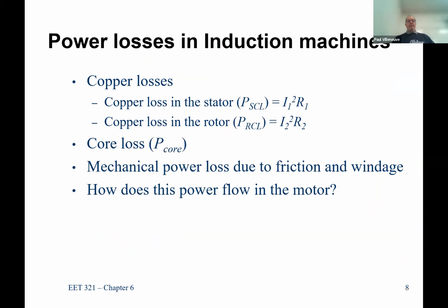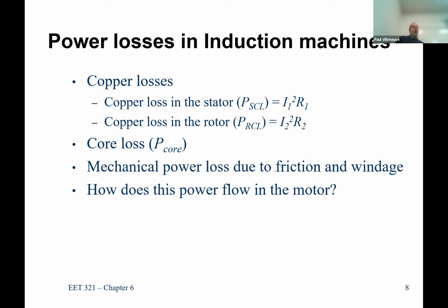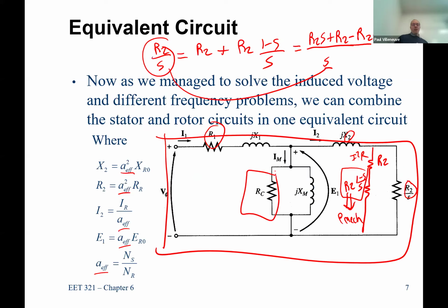And now we can finish with this, right? So we have I squared R, primary, rotor and stator, secondary and primary. We also have core losses. What do you know? Just like in a transformer. Now we have some mechanical power losses, but those are downstream, right? So all after here, now I have to start subtracting friction and windage losses.